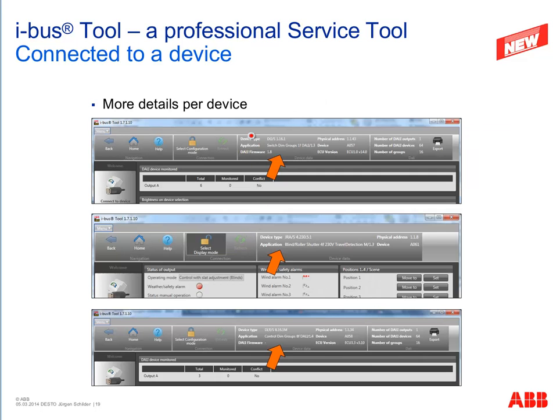So on the top here in this main menu you get more information or more details about your KNX device. At first here again the name DGS161, the version of the application Switch Dim Groups 1.3. This is the ETS application, and here we can see the DALI firmware 1.8 for example, and the physical address of the device, and the name of the device and the ECU version.